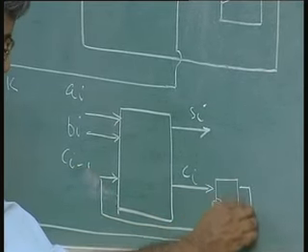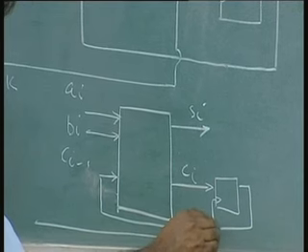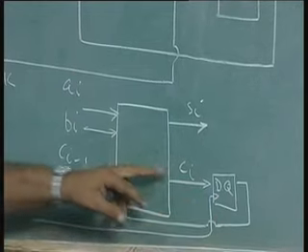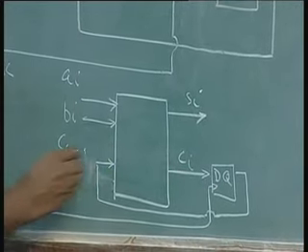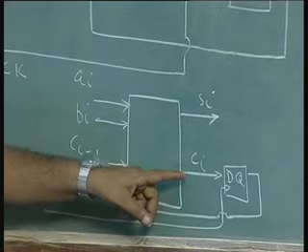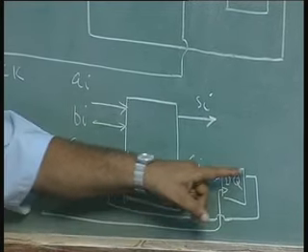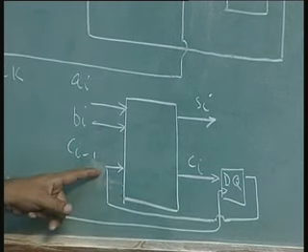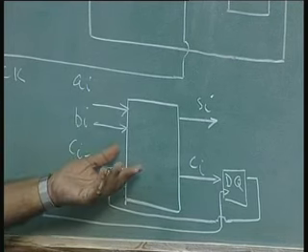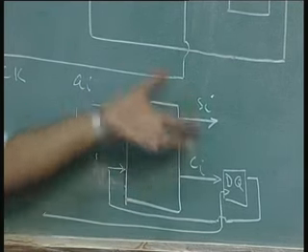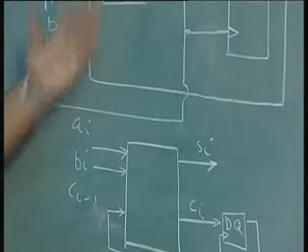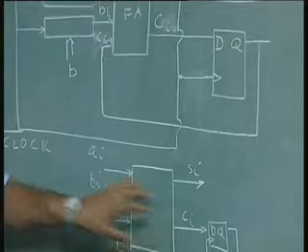See, this concept of flip flop output, the state variable input, resulting in combinational output and state variable outputs. The state variable output is used as state variable input again for the next clock period along with the new set of inputs Ai and Bi. This combination, this model we discussed in the last lecture. So, I thought I could give this example, so it fits into this. You see, this is the combinational logic.